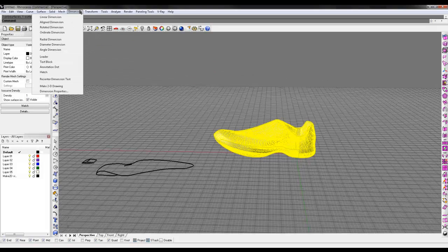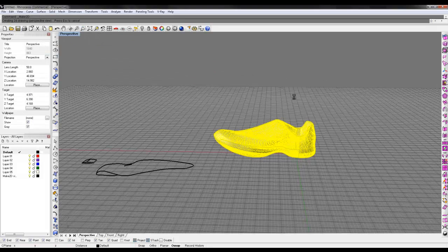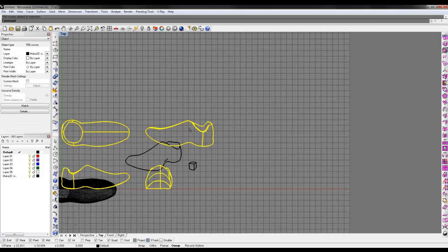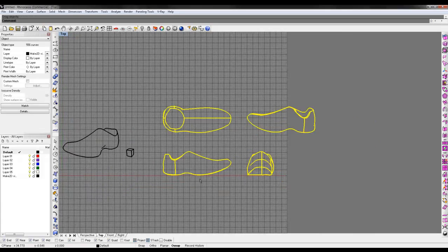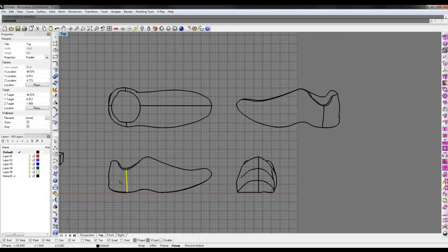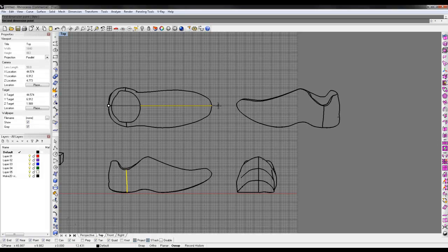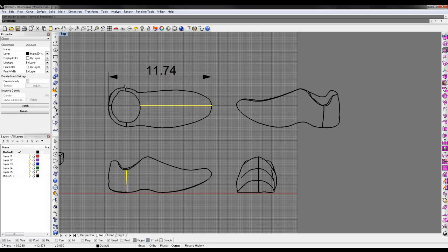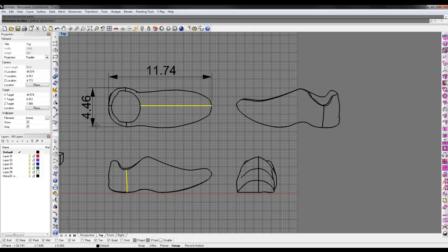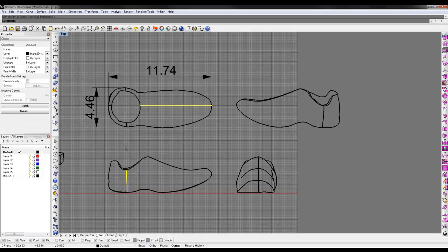And if you want, like I said before too, you can also use this to create orthographic drawings for pulling dimensions. It's going to take a little bit longer, obviously, because there's more information. It's got to draw top, front, right, and perspective drawings. And when it's done, it'll draw all your views that you have set up here. And you kind of have to go through the same thing, deleting your creases and everything. But then you can export this out to Illustrator or whatever vector-based software, or Photoshop or whatever. But you can then pull points off of this, and this is a great way to kind of rough out your dimensions.